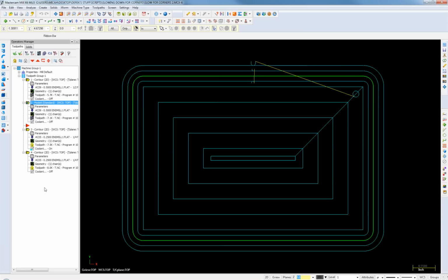Okay. Right, that's what I was thinking about was the older machine, because a lot of the older machines don't have a good look ahead. So when you start getting over 60 inches a minute and there's small data, it starts to actually choke. In this case, the machine might have a different type of look ahead. Sounds like you're saying the same thought, Mike. Instead of choking where it stutters, it's just slowing down. Would you agree on that?